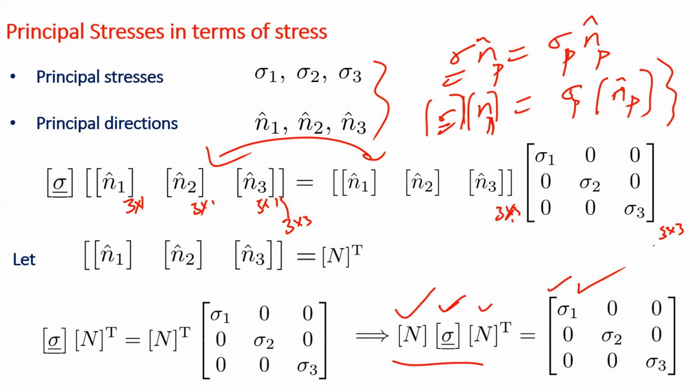We already know how to solve an eigenvalue problem. So I'm just trying to write the final outputs in terms of the original stress tensor. Just so that in the case when we know our normals, or when we know our principal stresses, or when we know two sets, we should be able to identify the third one without actually going through the long process of taking a determinant, then solving the system of equations.